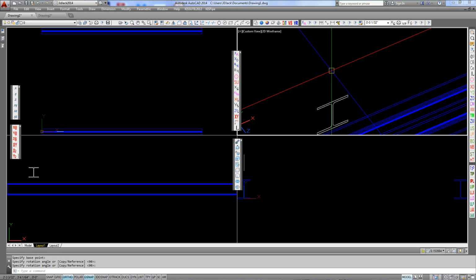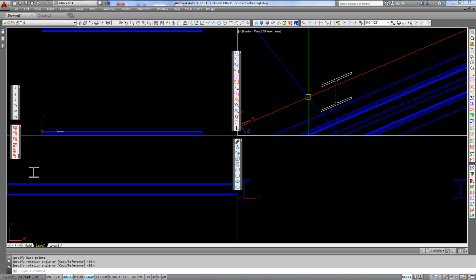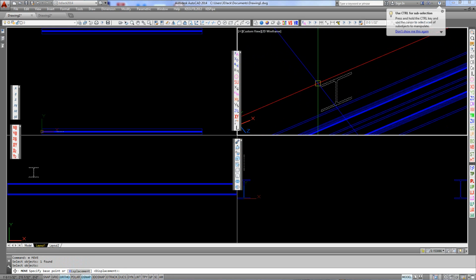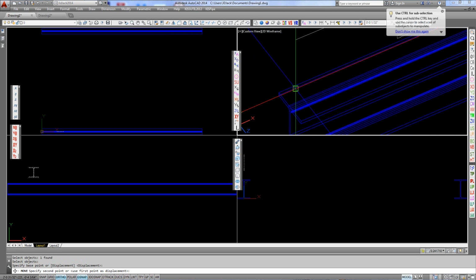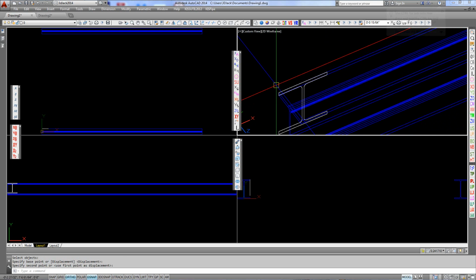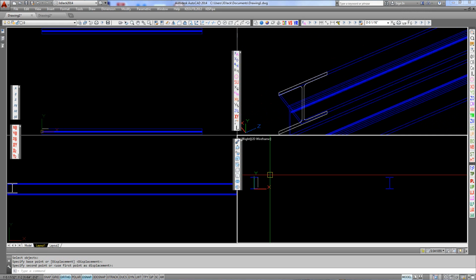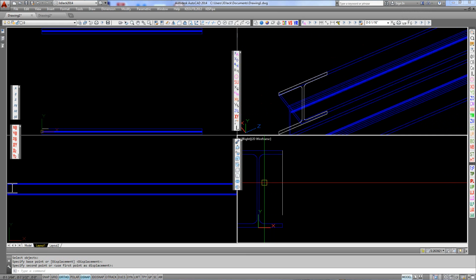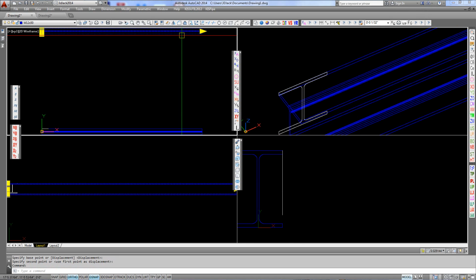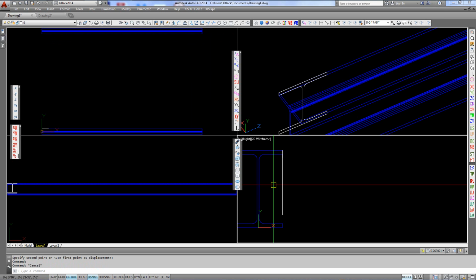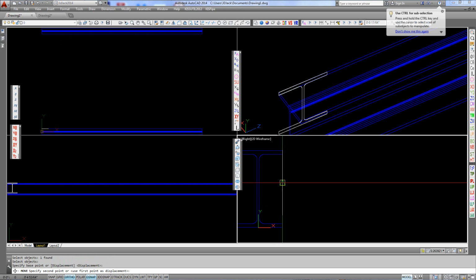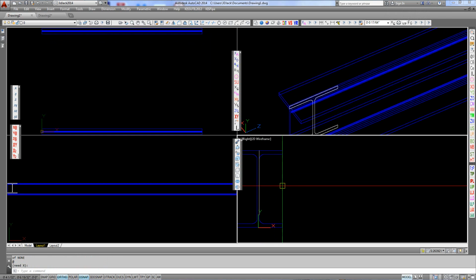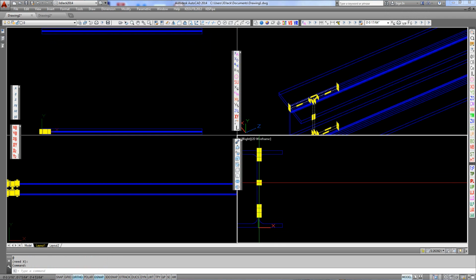Now we have to position it so that we can eventually extrude it and it'll be correct. So we get this upper corner here, then we go to the upper corner of this. We now have lined that up correctly. Now we know we have to go from the face of this beam to the face of this other beam over here in this viewport. So we need to move this so it is up against this face. If we do X at and we pick right here, that's now tied up against the face of this, and you can see it in these other viewports.